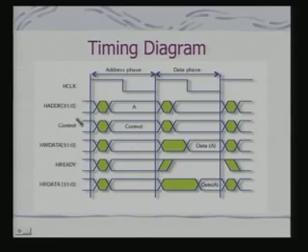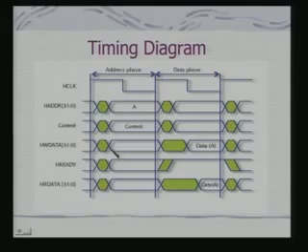In fact, the address is provided on your HADDR line, and you have the control information coming in. This control information is also provided in the address phase to prepare the devices for the targeted transaction. If it is a write operation being initiated by the master, the data should be available at this point itself. And if and when there is this HREADY signal, what happens?